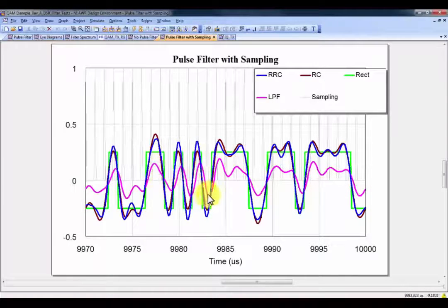So you could do this by hand and try to compare, but a nicer way to do this, and the way that industry does this, is to look at what's called an eye diagram. And this is basically an eye diagram that helps you take a long series of data and see how well it is lining up with a synchronized pulse stream and how well you might receive that data. So what I'd like to do now is actually look at a cartoon example of an eye diagram. But before I show you the eye diagram, I'm going to show you how it's constructed.